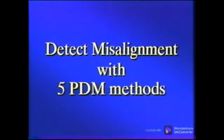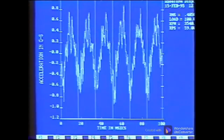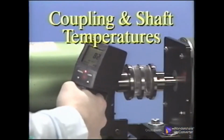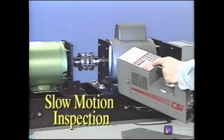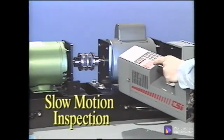Misaligned conditions can be detected using at least 5 predictive maintenance methods that do not require an interruption of the process. They are spectral and waveform analysis of vibration data, as was shown earlier, phase analysis of vibration data. Another is to measure coupling and shaft temperatures using an infrared temperature probe or infrared thermography. And the strobe light can be used to actually see shaft, coupling, or machinery movement in slow motion.